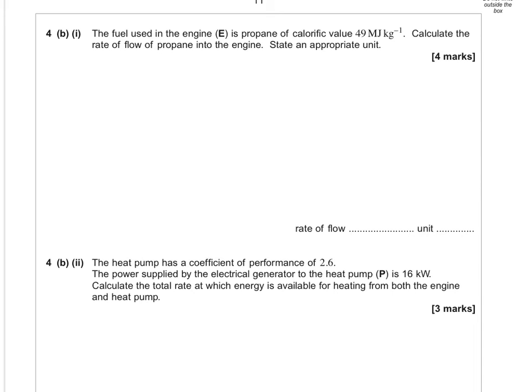So the first thing here is going to be calculating the efficiency, so we can work out the input power. The maximum theoretical efficiency is going to be given by (TH minus TC) over TH in Kelvin. So let's dig up those values. It's going to be 1600 minus 290 over 1600. 1600 minus 290 divided by 1600 gives us 0.81875, and so on.